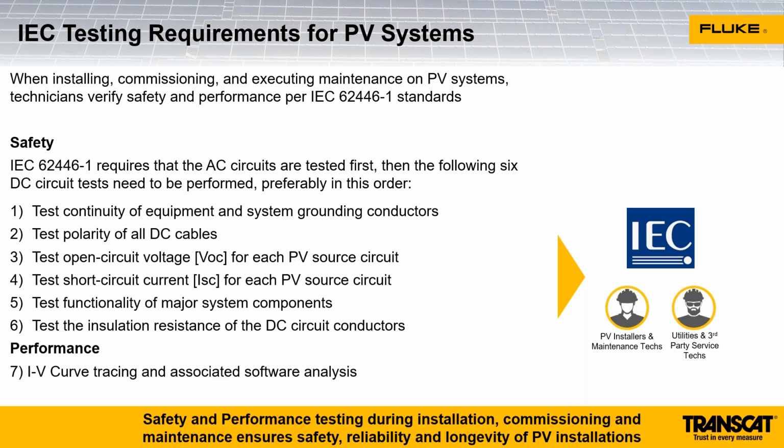Now, the second class of tests in the 62446-1 standard is for performance. And this would be IV curve tracing and analysis of the IV curves to ensure that the modules or strings of modules are working as you would expect them to.